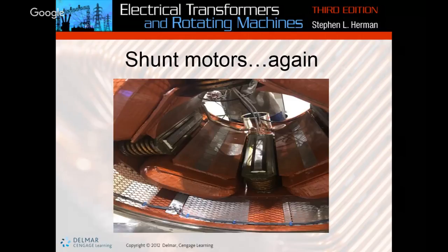So that's just telling me the difference: the shunt wound motor doesn't have a great starting torque, but it can maintain any sort of speed. So once we get this thing running at full speed, we can almost lock this thing down, put as much load on there as we can, and it's going to try to maintain its speed. Of course, if we get too big of a load on there, we will lock the armature up, and we won't be able to turn it just because of the huge amount of load on it. That's just locked rotor.